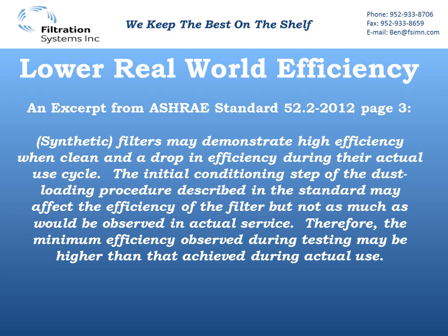Right on page 3 of ASHRAE's 52.2 standard 2012 revision, they couldn't start any worse for synthetic medias than this. They say right on page 3, synthetic filters may demonstrate high efficiency when clean and drop in efficiency during their actual use cycle. It goes on to say the initial conditioning step of the dust loading procedure described in the standard, also known as Appendix J, may affect the efficiency of the filter, but not as much as would be observed in actual service. Therefore, the minimum efficiency observed during the testing may be higher than that actually achieved during actual use.